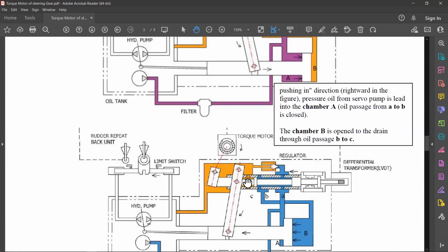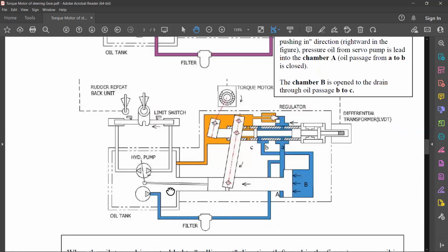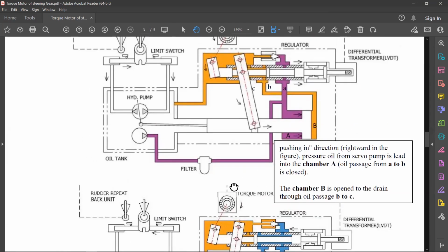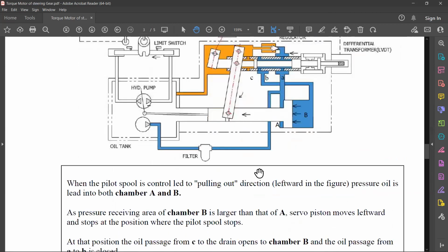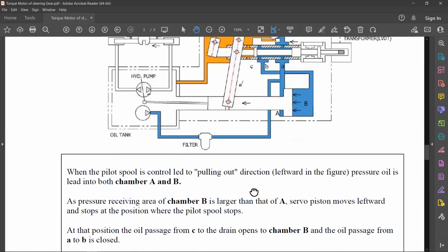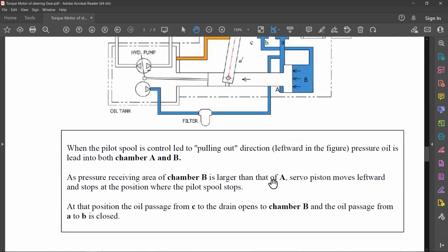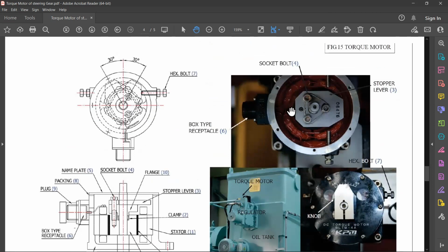Okay, so they control the spool piston operation, and as the spool piston is operated, simultaneously the hydraulic flow will also take place, either in the port or starboard direction. So this is the emergency control which is replacing the spool piston operation for the telemotor operation. In the telemotor which we saw, emergency control was there. So this is part of that.